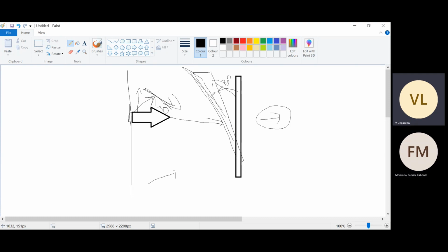The position should be optimized in order to see that the horn is in that particular position. So the horn will remain facing the same direction, but the reflectarray will be pointing like this. Then you can see here we are able to achieve 30-degree again, but it will be tricky because we have to rotate the reflectarray by 30-degree and also offset it, by whatever dimension we have in the XY coordinates.